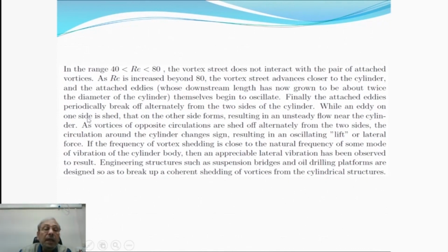While an eddy on one side is shed into the stream, one grows on the other side, resulting in an unsteady flow near the cylinder, in the near wake of the cylinder. As vortices of opposite circulations are shed off alternately from the two sides, the circulation around the cylinder changes sign, resulting in an oscillating lift or lateral force.